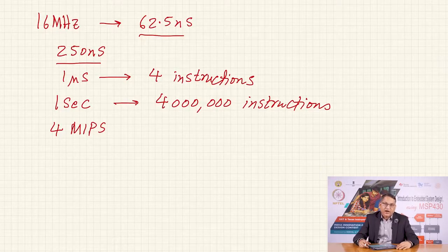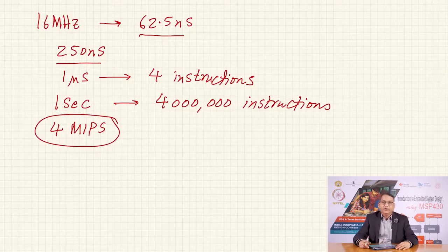Human interaction, on the other hand, the act of pressing a switch and releasing it, is a much slower process. Which means if a human is going to press a few switches, at this rate the microcontroller will be able to scan and poll many switches in 1 second. Even so, you would be deprived of executing the actual program while the microcontroller is waiting for a switch to be pressed, and therefore, this idea of interrupt is brought into the picture.